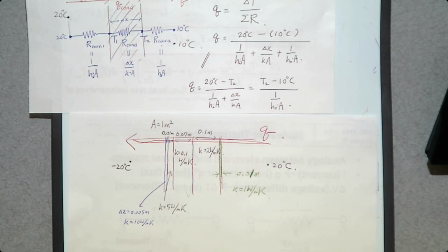So you need to run a refrigeration cycle to remove heat in the same amount of this Q so that you can maintain constant temperature inside. So let's determine this Q. How can we do that? You can use thermal resistance network.